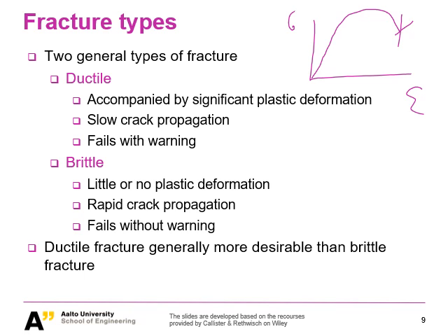But the very important, very practical characteristic is that ductile fracture fails with warning. So what does that mean? The warning means the crack shows with a small crack initiation, and you can really see it develop, right? This corresponds to the slow crack propagation as well. But beyond that, for example, you don't always see something in service.